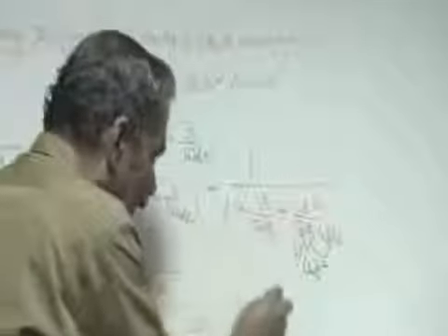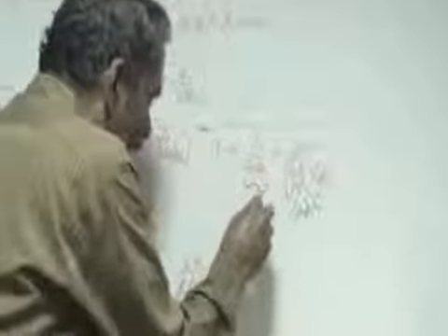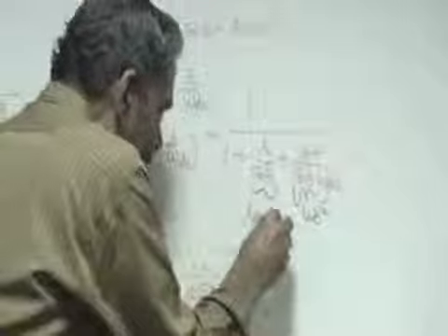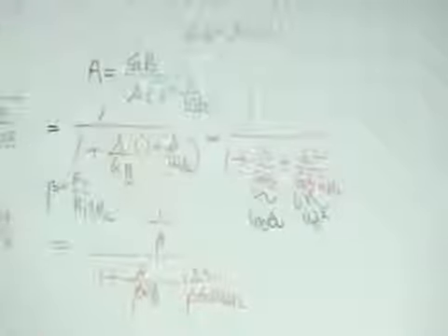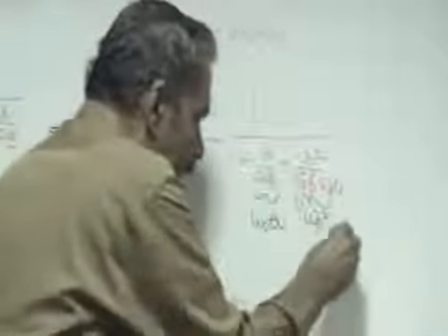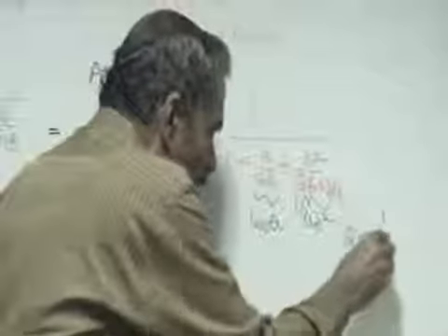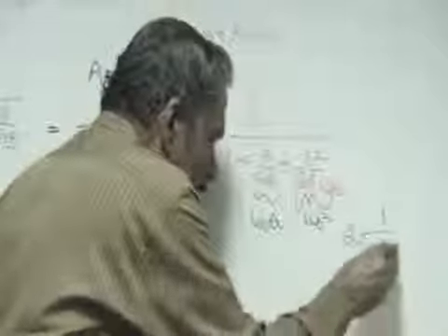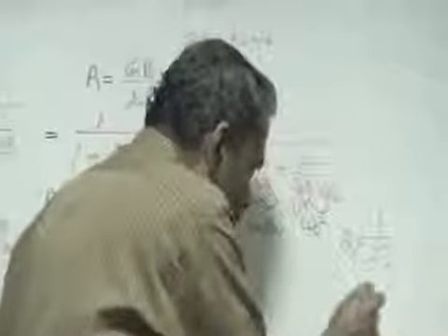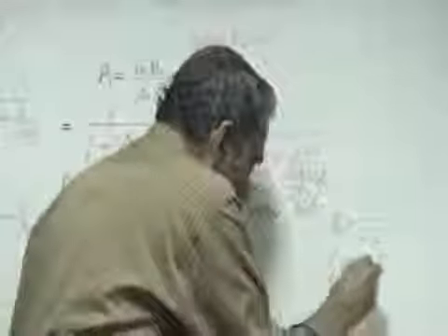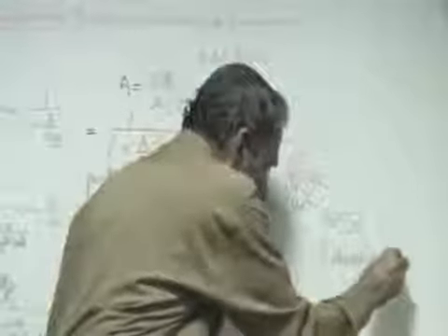Omega naught is the natural frequency of the system, and this is going to be written as omega naught over Q. Q is called the quality factor, and it is equal to 1 over 2 zeta, where zeta is called the damping factor, which is familiar to control system engineering. And communication people call 1 over 2 zeta the quality factor Q.